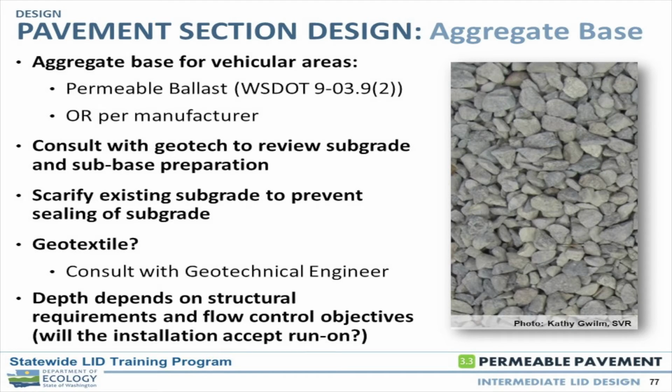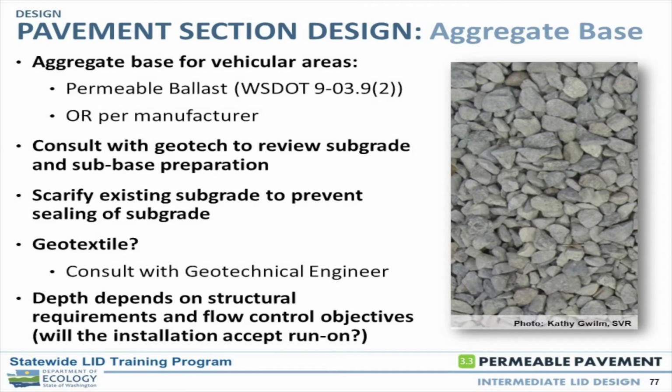And so we really want to maintain the infiltration capacity that we've just measured through our process, and to maintain that, it's about getting just the right level of compaction and scarifying the surface so that we have a relatively irregular interface between our reservoir course and our subgrade. And then we mentioned geotextile again, probably not. And then setting the depth of that material, mostly based on hydraulics, but then also probably some minimum depth as well to make sure that our section is met.